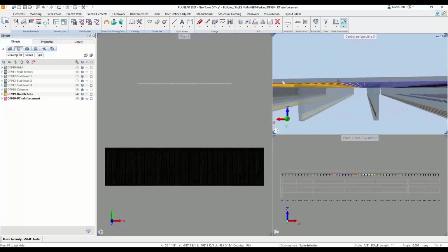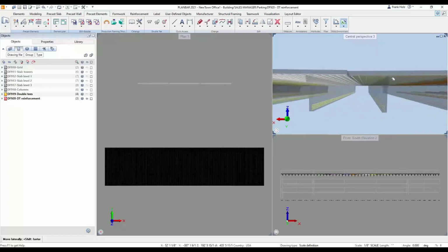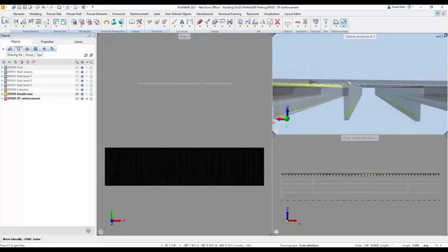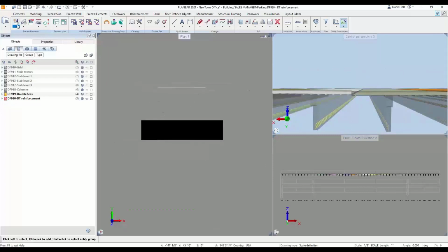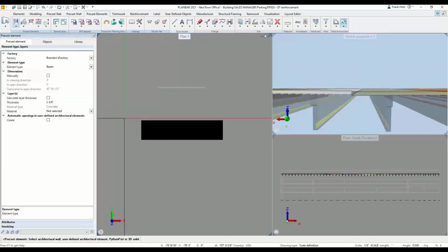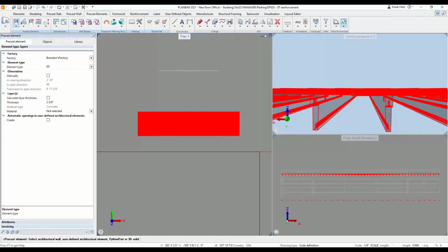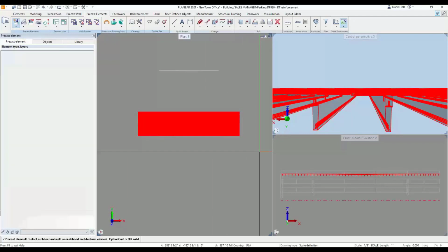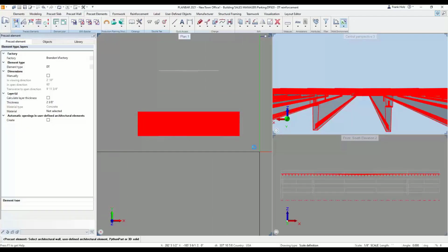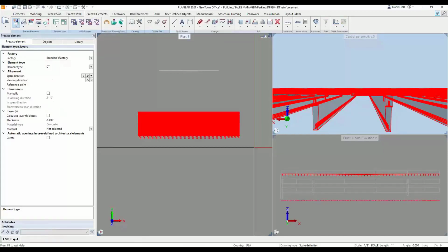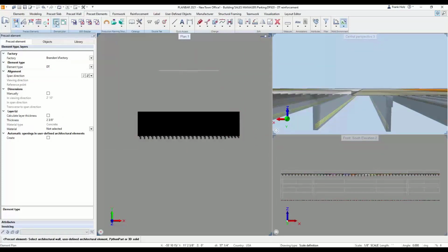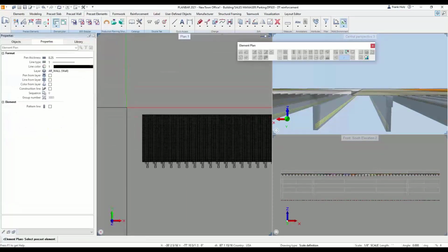So if I need to open something up for utility conduits somewhere, and I need to have the mesh be opened up around it and maintain clear cover, I can do that without affecting the other elements, and it will create me a separate mark number, a separate shop ticket, a separate bill of materials. That's right. And you'll notice I was going around in the 3D just to highlight the point that these are now unwarped. So it's taken those, it's unwarped them, made it a flat shape, which it will be in until you place it on its bearings, and then it actually rests or settles into position there.